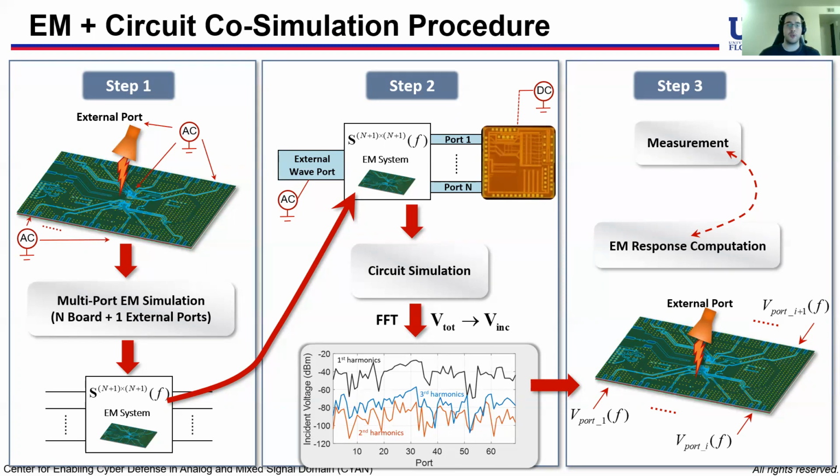After the simulation, we will obtain the total voltages on every port of this board. We then compute the Fourier transform of all of these voltages to obtain frequency domain voltage of the fundamental frequency, second or third harmonics.